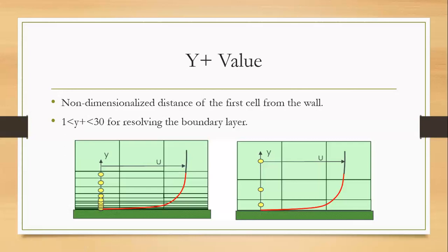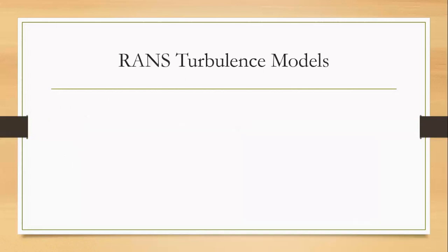So this y plus value is what different turbulence models are related to, because for some models this high resolution is not needed, as there are already some corrections implemented. So we will check out the turbulence models now and discuss it there.